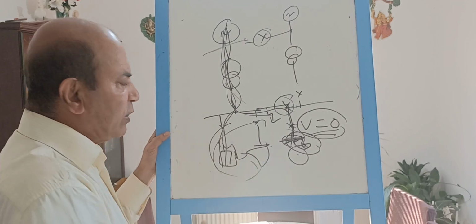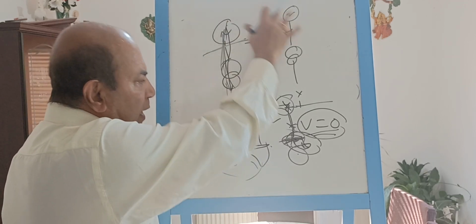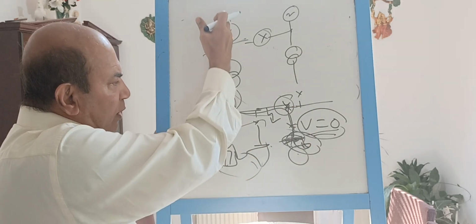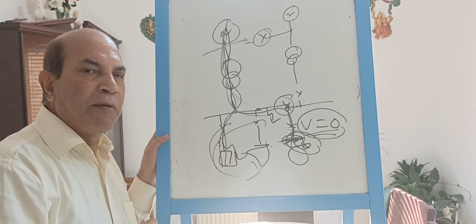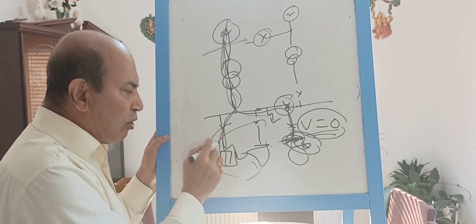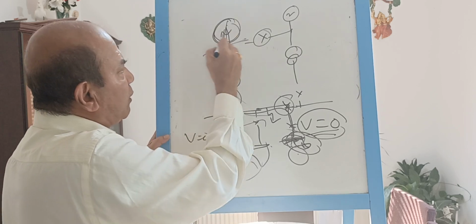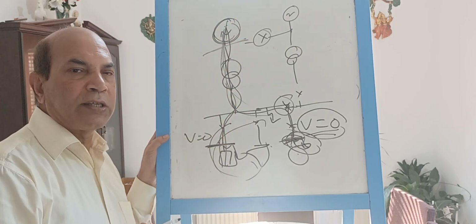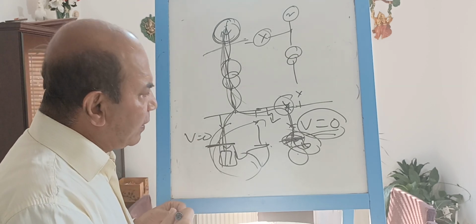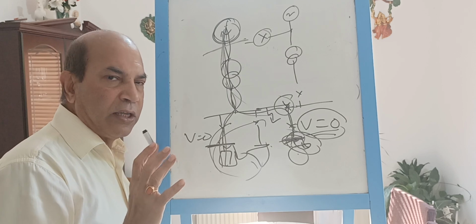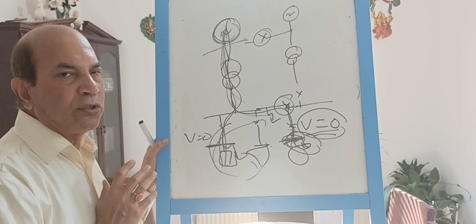So during the short circuit, how much impedance will come into the circuit will not be decided by the entire circuit. We first have to draw the short circuit flowing path, and on that path what impedances will come into the picture. So this is another point, and at the short circuit point we have to consider there is no voltage. So only this source voltage is present here which is supplying this short circuit current. So this is another assumption, or another condition we need to consider to calculate the short circuit current. So this is the total of the preliminary parameters to be considered.